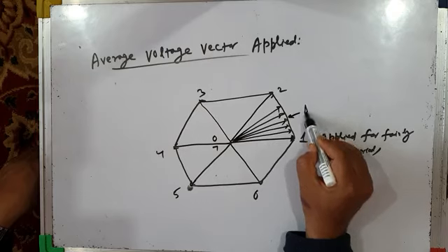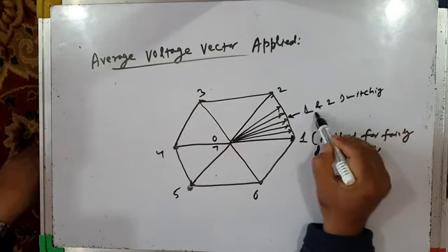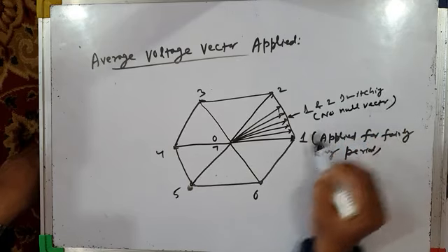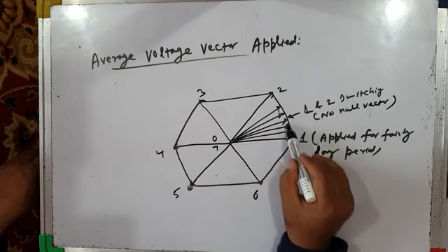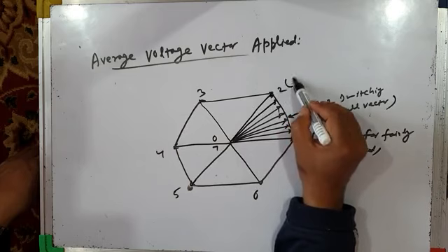During this period, 1 and 2 switching, no null vector is applied. So that means your reference vector moves along the hexagon till it reaches active vector 2, and it remains here for some time.